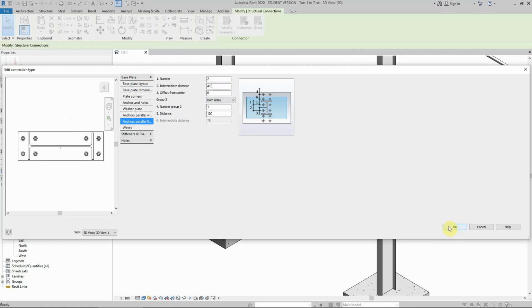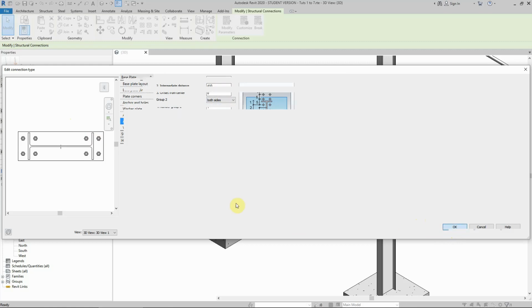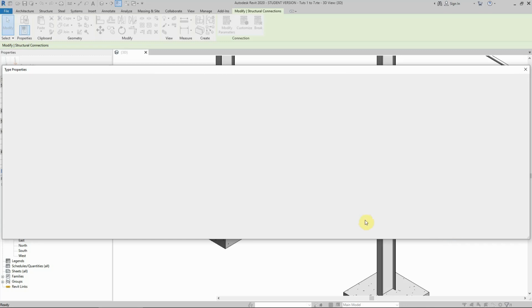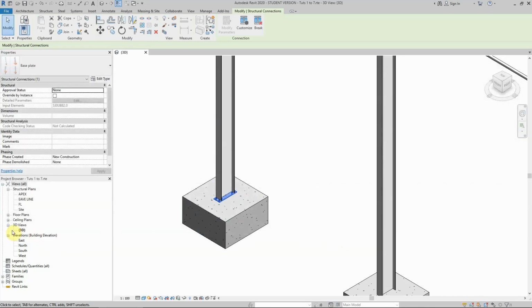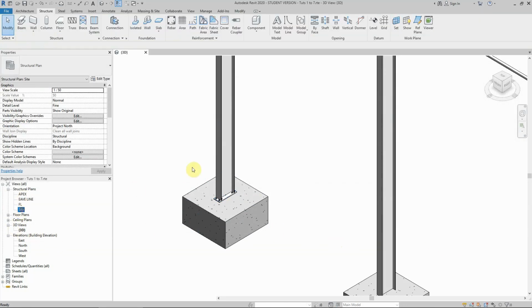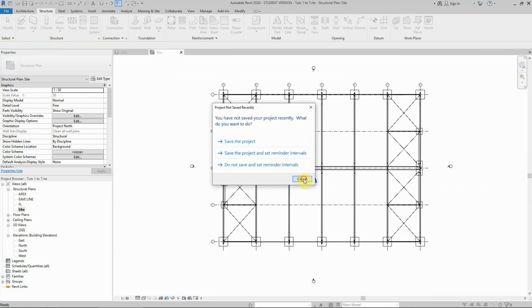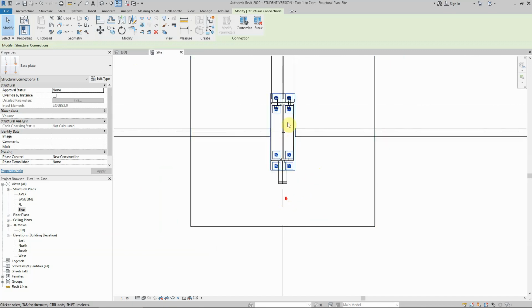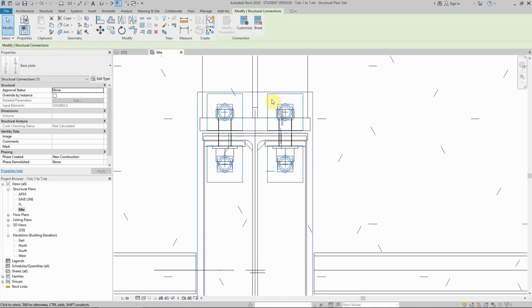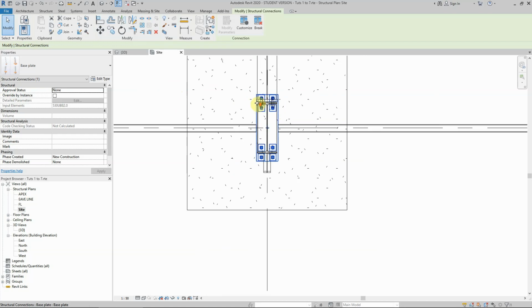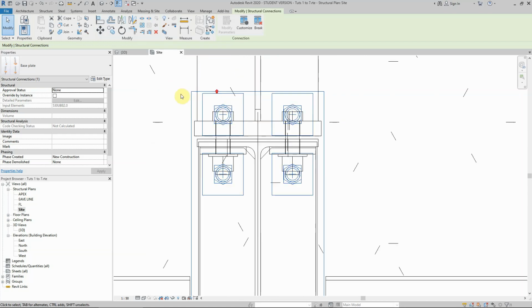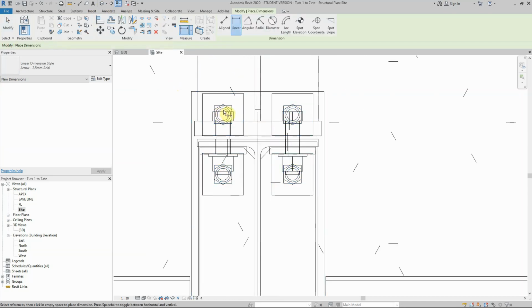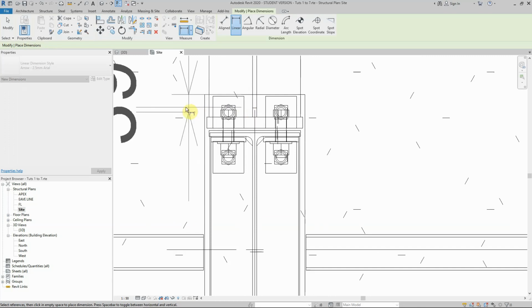Let's remember those. I can go and just check these measurements and see what adjustment I need to do. If I go to the side view, this is the one, I can just measure from here. Now what we need to measure, this is the base plate. If I look at it from the center of this bolt here to the edge of this base plate, I've got now 39.